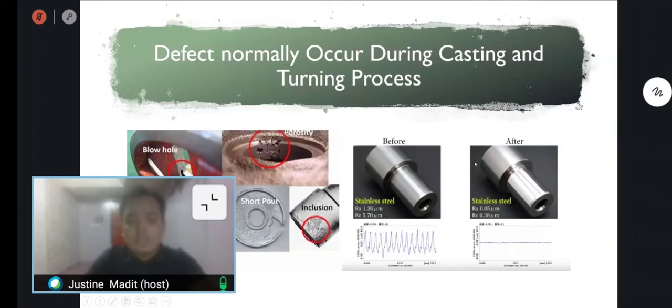For a better turning process, the thicker the metal, the slower the speed should be. Besides that, this normally occurs because the tool bit is not sharp enough. You need to sharpen the tool.